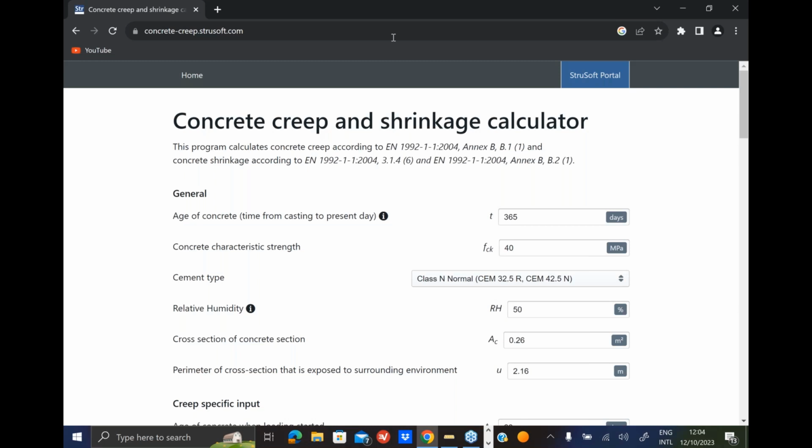Therefore, this excess water is what is causing the shrinkage. And of course, it depends on the humidity, on the temperature, on the shape and size of the concrete element, and the curing process, either normal moisture or steam cured.